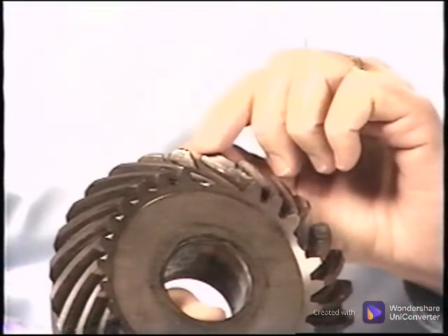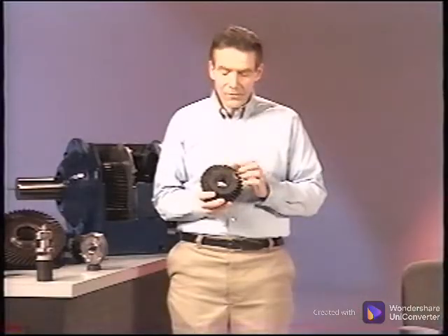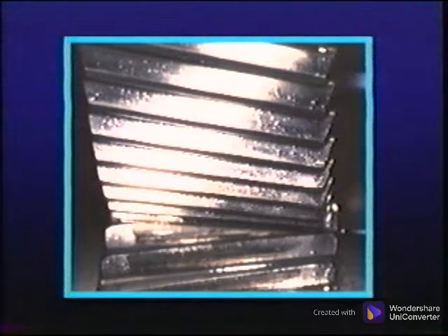Of course, some problems are obviously more severe than others. A broken tooth can indicate excessive loads on the gear and puts undue stress on the other teeth. Wear adversely affects the gear meshing action, but the gear may run longer than a gear with a broken tooth. How can we distinguish one defect from another?